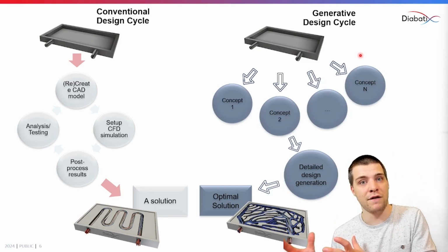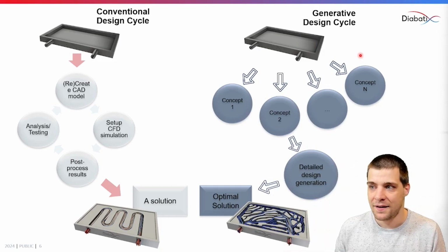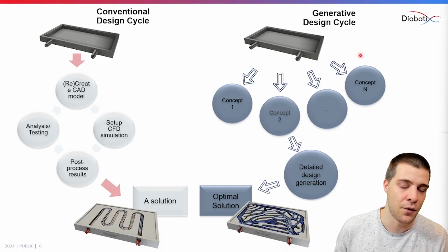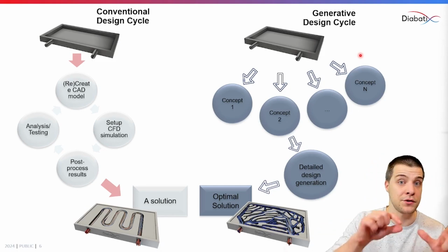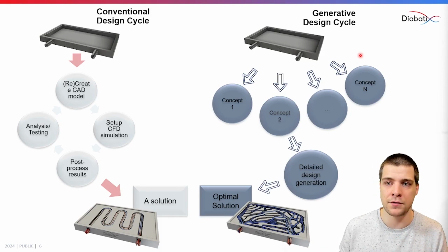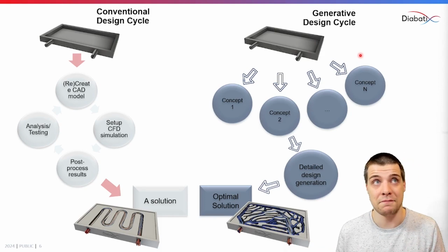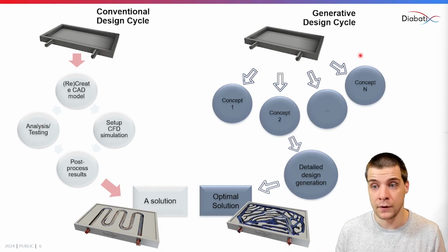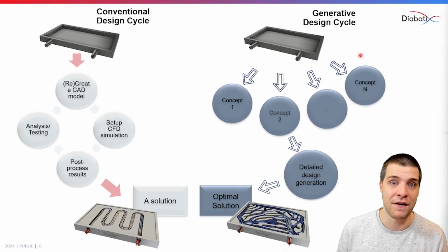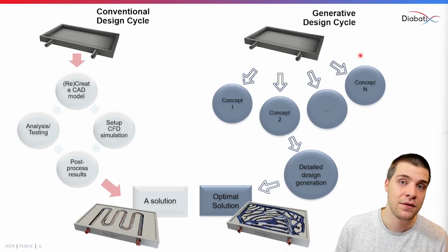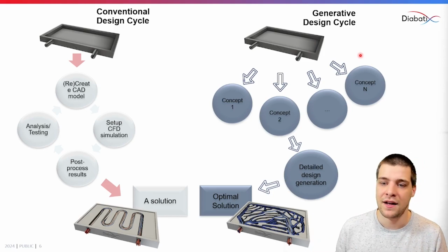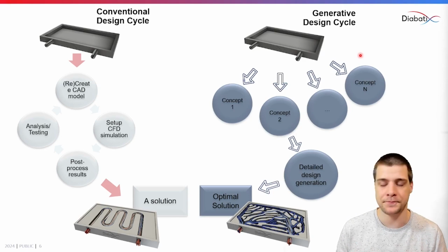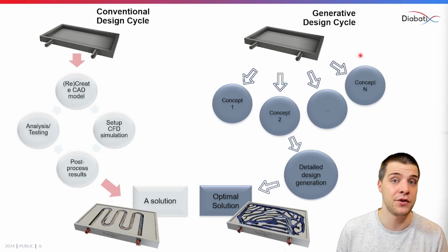If you're very far, for example, if you exceed it by a huge margin, then you know whatever design you put on it, it will never work, and then you'll have to revisit the positioning of the chips, either remove a couple of chips or choose more expensive chips that produce less heat, or vice versa. If you're very far below the temperature limits, so you still have quite a bit of margin, you can consider reducing the overall size, making everything a bit more compact, which in general makes it more difficult to cool down.